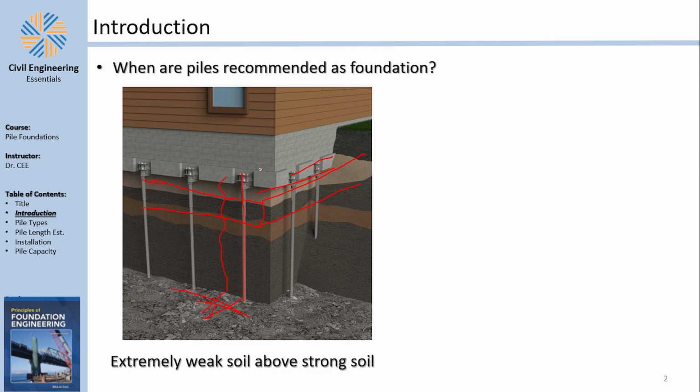Now, this is usually the case if you have reclaimed land. This happens in some countries where there's a large beachfront and they want to extend their beaches by reclaiming land, because when you reclaim land, you're actually burying the sea, which means the top layers are not historical layers, which might be weaker than the other historical layers. So yeah, that's case number one.